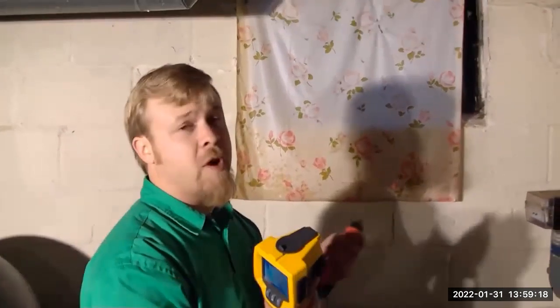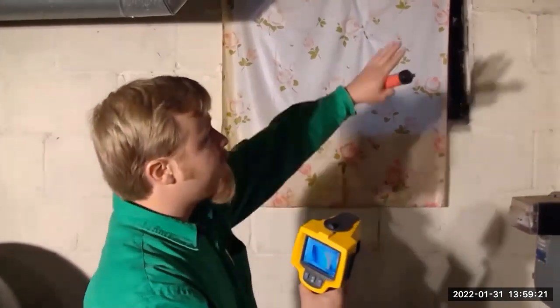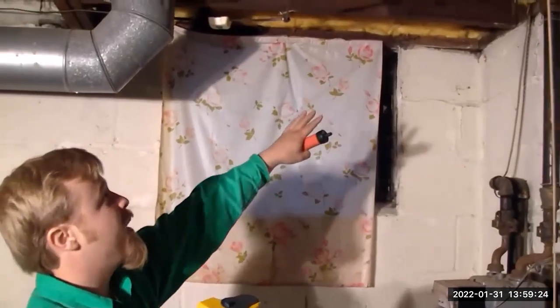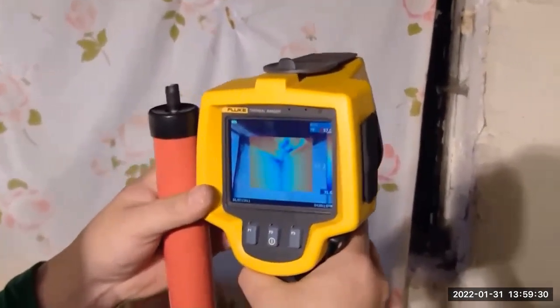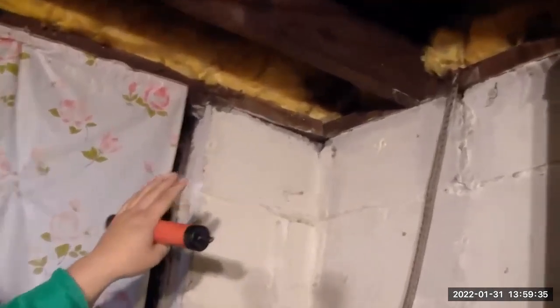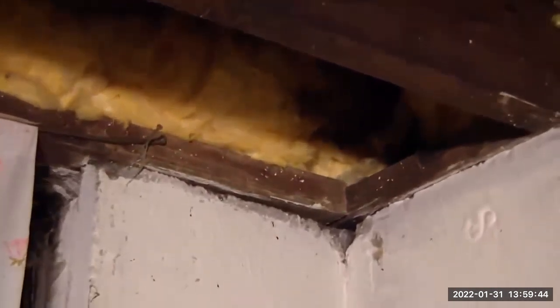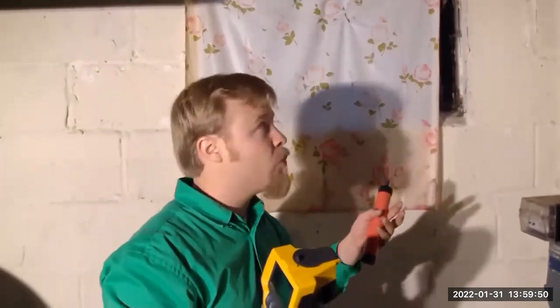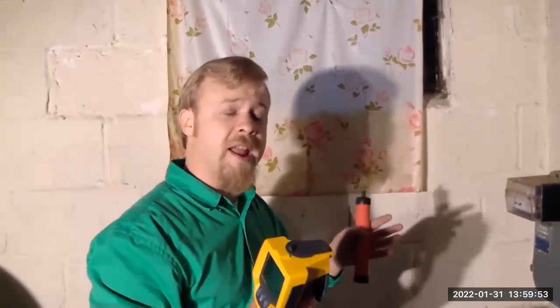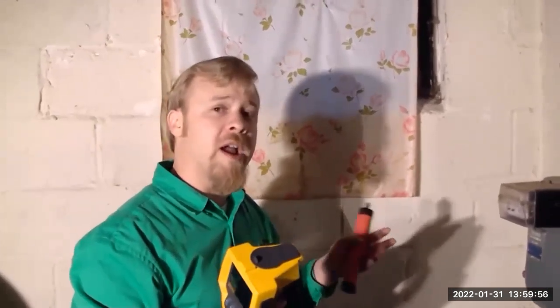Now we're in the basement, and one particular area that you really want to focus on is what's called the band joist or the rim joist. And what we found here is someone has insulated the band joist, but as I shoot with my camera here, there's actually low 30-degree air coming in through that insulation. And if you look up inside there, it's starting to actually blacken the insulation because it's basically acting like a filter at this point. So typically what we always recommend you have done, instead of insulation such as this, is foam insulation where you're going to get an air barrier to stop that air from coming in, as well as a thermal barrier at the same time.